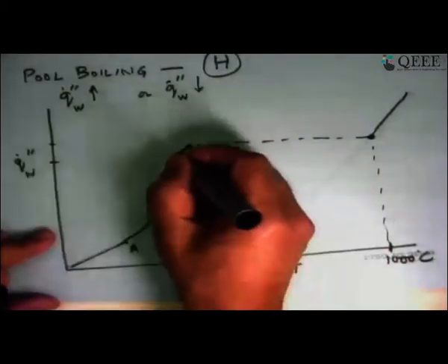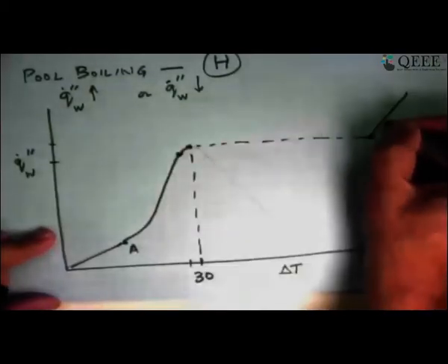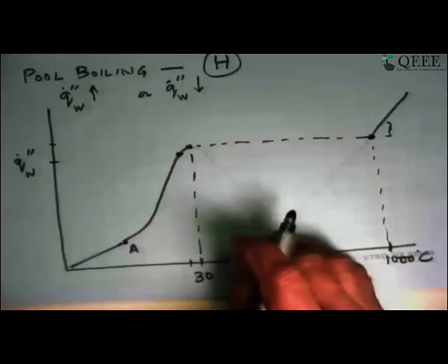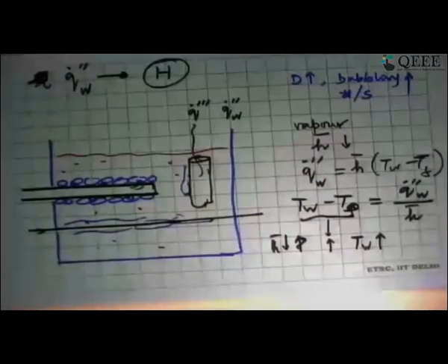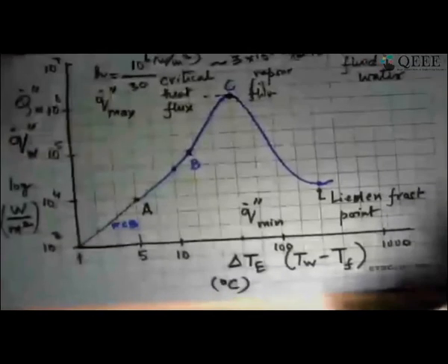So a 10% increase in wall heat flux is enough to cause it to go from this safe operating condition to somewhere in this region, which suddenly shoots the temperature of the material, causing it to fail. That is the danger for almost everything, and this is how the word critical got attached to it. And this peak ended up being called the critical heat flux.